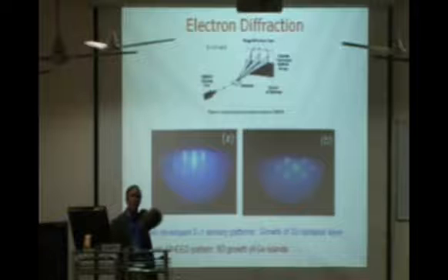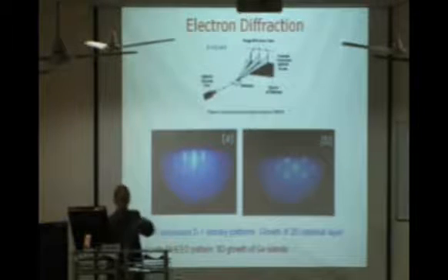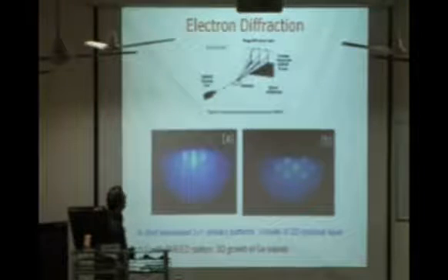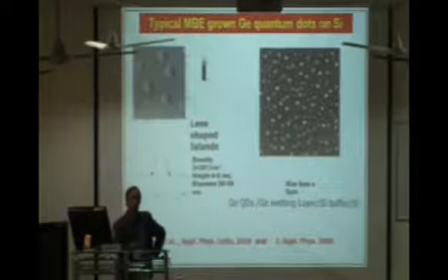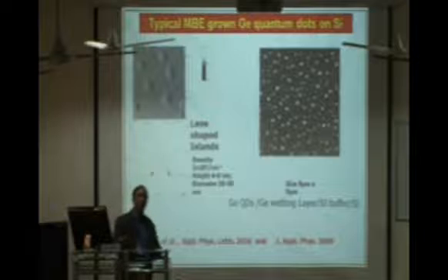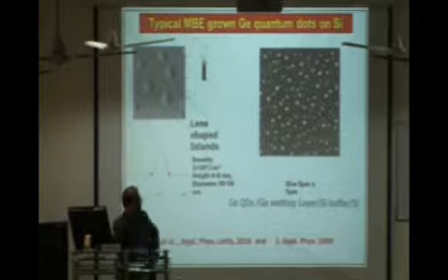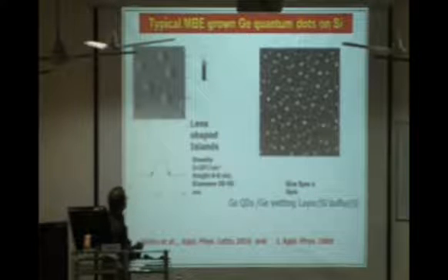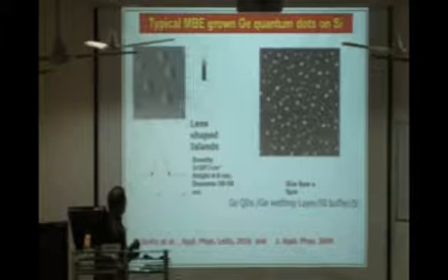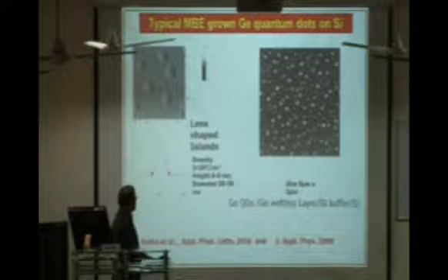So you know that now there is a formation of the 3-dimensional quantum dots or islands, where the growth can be stopped and they can be used for making some kind of devices. Not necessarily are they spherical in nature; their shape is decided by thermodynamics, and you have to see the Gibbs free energy calculations for different kinds of shapes. Typically they show pyramids, hearts, and domes.